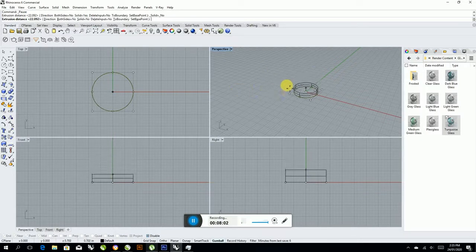Okay, but before you create it to see it in a shaded form, what I'm going to do is that we need to go up here and look at the command line. Okay, I told you you'll be looking at the command line a lot. It is showing me what to do. So it's actually telling me if I want to create the 3D object using both sides, or if I want the 3D object having an open hole within it or not.